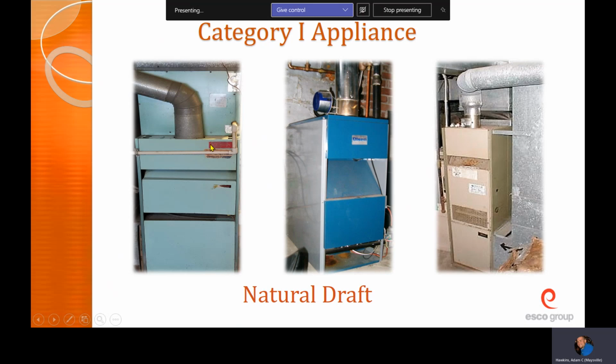So that's a good sales point, if you know the efficiency that furnace is supposed to run. And then let's say you could figure out how to do a combustion analysis to see what it's actually doing. You could calculate how much fuel they're wasting every year, every month, whatever, based on their efficiency. If they're 65% efficient, if they're inputting 100,000 BTUs of fuel, but they're only getting 65,000 BTUs of heat out of it, you can do the math pretty quick and say, okay, you're wasting 35%.